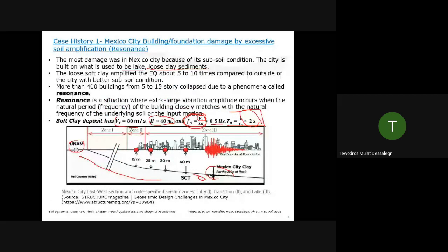This is the first analysis you do. Once you understand your soil from your lab tests or geophysical investigations, you should expect some amplification. See how the rock motion is amplified. See how the energy content is wide. That's because of the soil. So this is purely amplification.